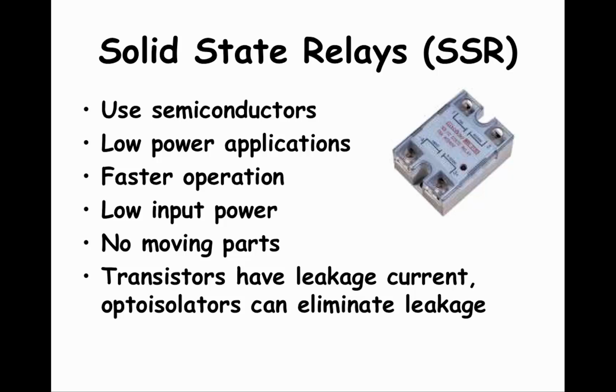One disadvantage of solid-state relays is that some may have what is called a leakage current. A leakage current is the current flow that continues to pass through on the load side of the circuit, even though the control side of the circuit says to open the circuit. Leakage current is inherent in semiconductors. Leakage current may not be a problem with some loads, but if leakage currents are a problem, they can be managed with opto-isolators.